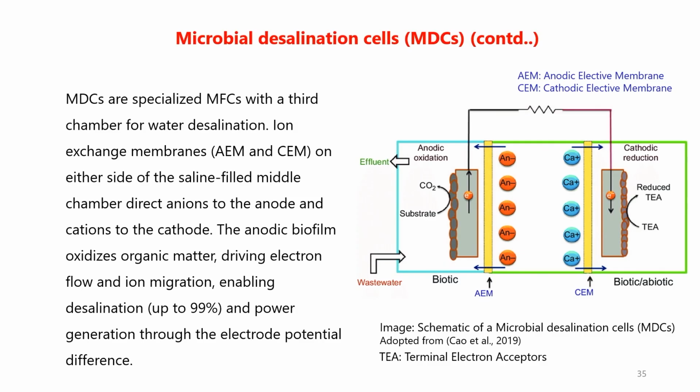MDCs are specialized MFCs with a third chamber for water desalination. Ion exchange membranes, AEM and CEM, which you can see here, on either side of the saline filled middle chamber direct anions to the anode and cations to the cathode.